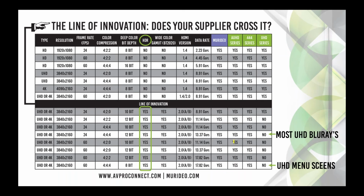Oops, let me go back up. Down at the bottom of this page are signals requiring almost 18 gig. 18 gig is the full spec for HDMI 2.0. And if you look at that, the menu screens on these new UHD discs are all running at about 18 gig: 4K 60, 444, 8-bit with HDR and wide color gamut.